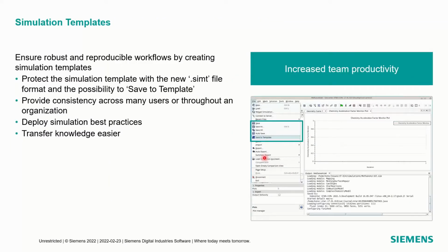All right, the next thing is simulation templates. Templates have always been possible to create, but there's never really been a system for them. Whereas in the past, you really just had to save a SIM file and then name it your template. Now you actually have a SIM file extension. So the concept has really been formalized in this version, and there's even a save to template button here to help avoid saving over a template that already exists, because I know that can be frustrating, and I've done that before.